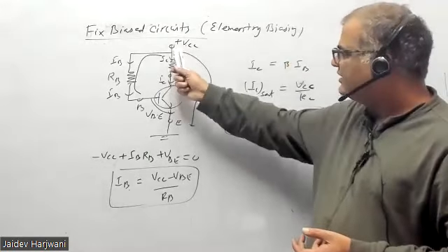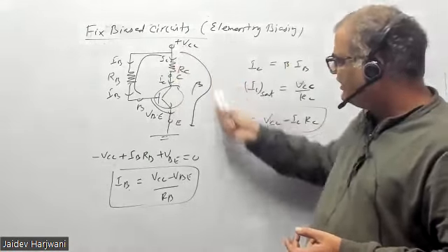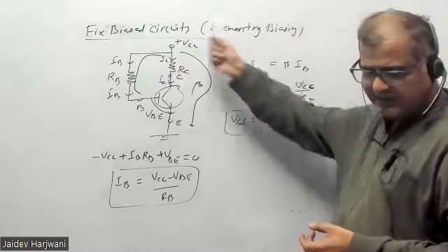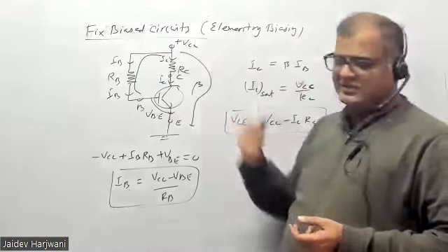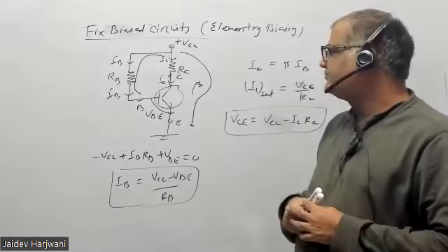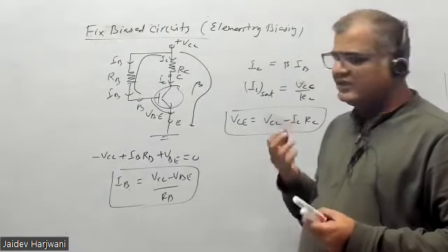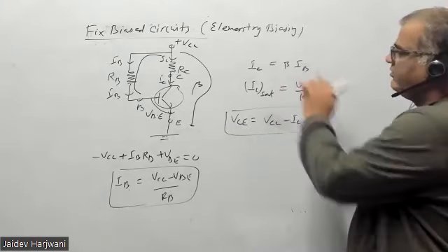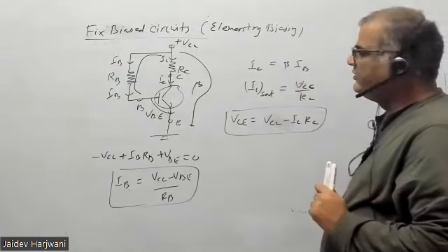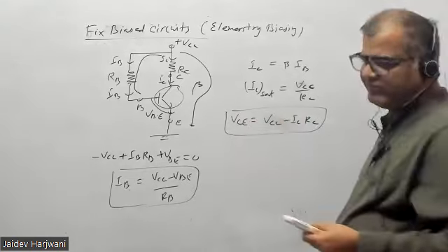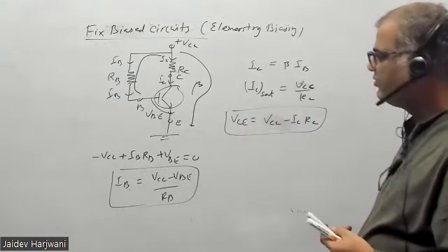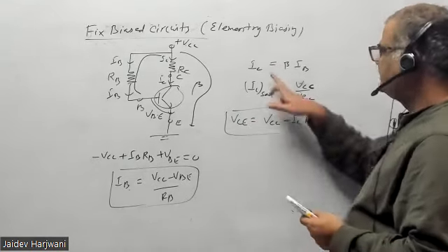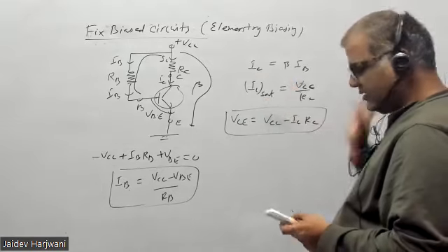Same as here, I can put one more transistor and connect the circuit, giving the biasing current to every transistor. But from a fundamental, operation point of view, IC is dependent on beta, so this is not practically used. But just from an exam point of view, any biasing can be asked in the question. So IC is dependent on beta.